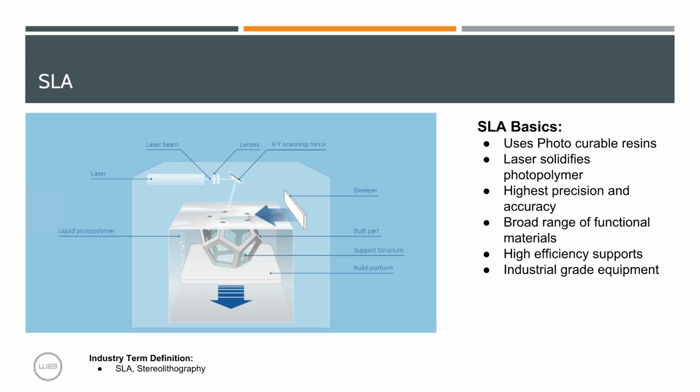So let me explain the difference between this and what you'll see in a consumer level 3D printer, for example, the Formlabs, another printer we use here in-house, great little printer for quick and dirty type prototypes. It actually inverts your part and fights against gravity to hold the part to the build plate. Well, what does that do? That causes some warpage. It also causes for the support material to actually be pretty thick and causes some blemishes on the part.